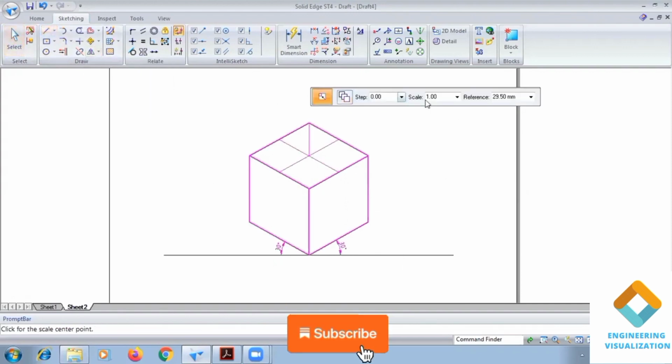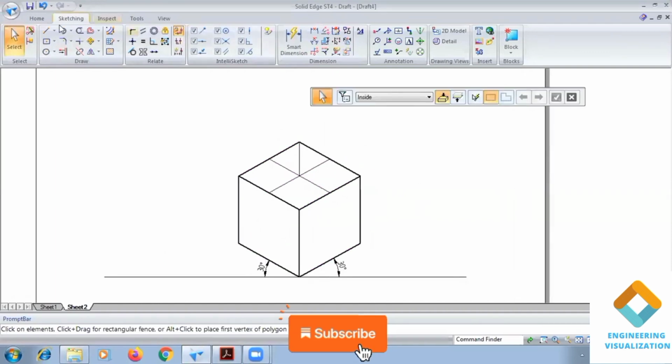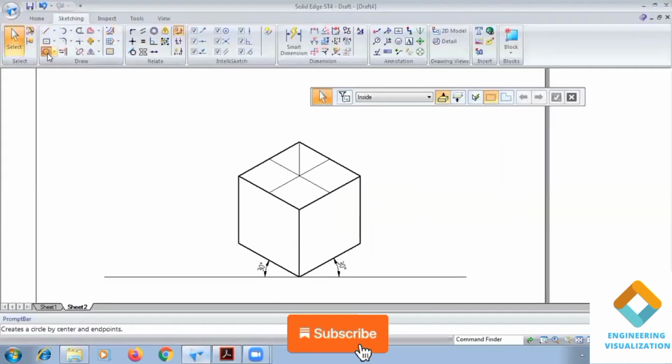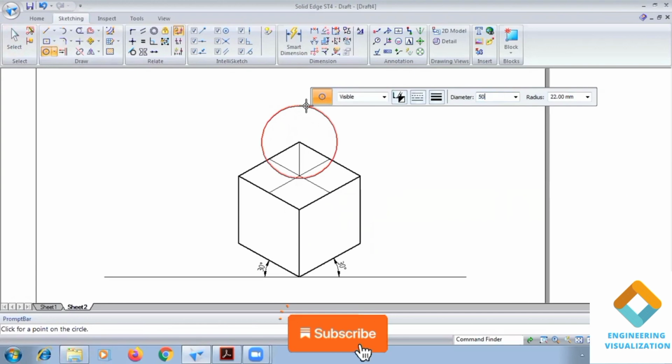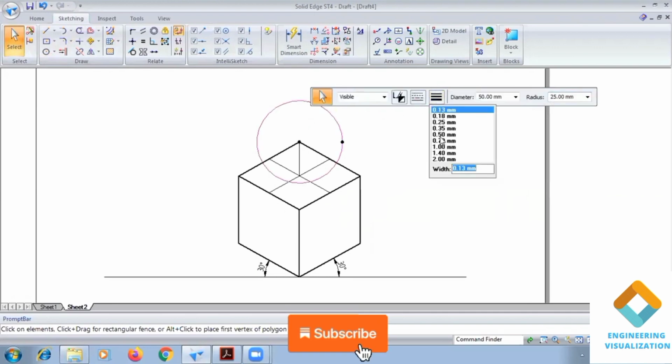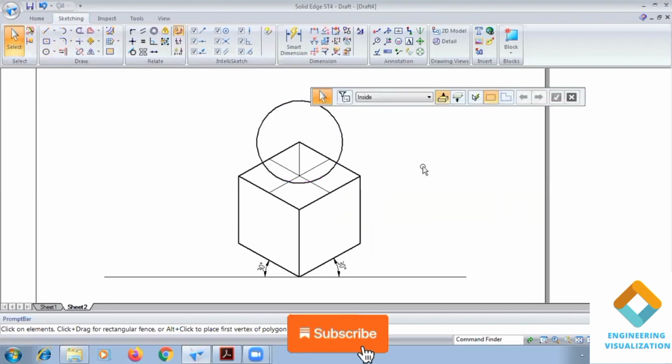Go to scale here, type here 0.816 or 0.823, you can type it. Okay, now go to circle and draw here. That's the center of the sphere. Now go to circle and draw a circle of diameter 50. Enter. So that completes the sphere here. So always remember, sphere will be drawn with the actual scale, other solids will be converted into iso.